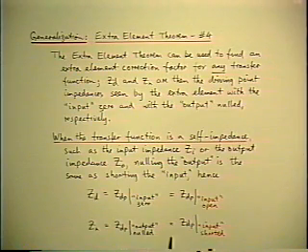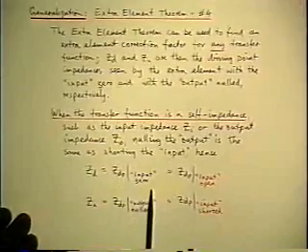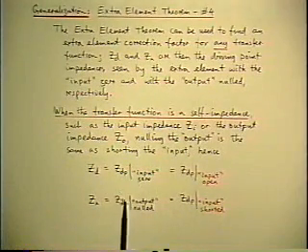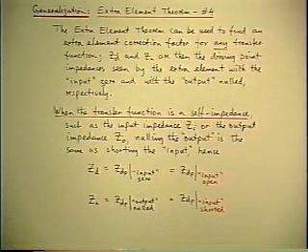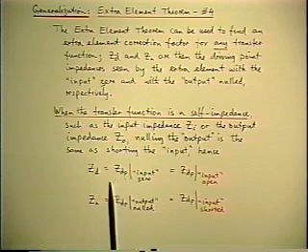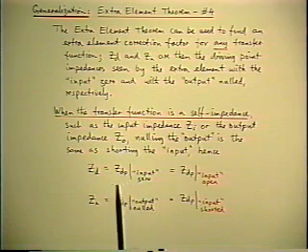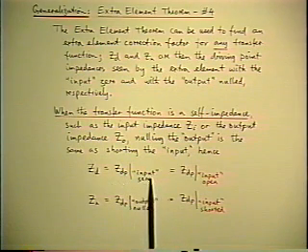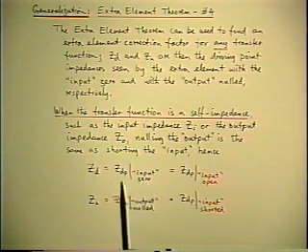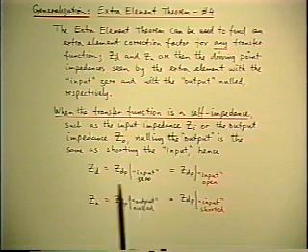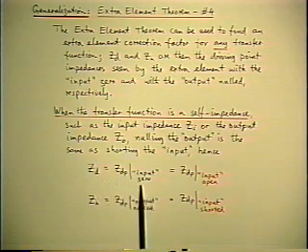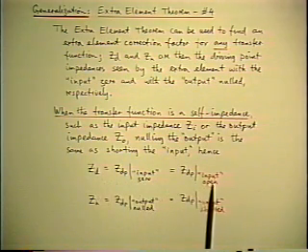And there is a special case of that when the transfer function is a self-impedance, in which you can shortcut the conditions for the calculation of the two driving point impedances. Z_D is basically a single injection calculation when the input is 0, which, in the case of a self-impedance, the input is a current, and so the equivalent condition is you calculate Z_D when the input is open.